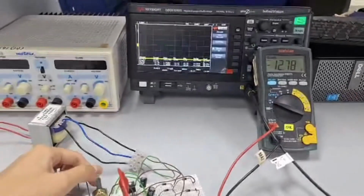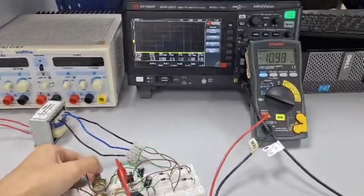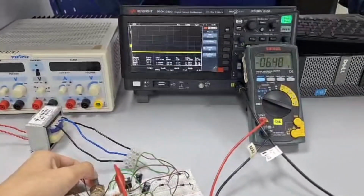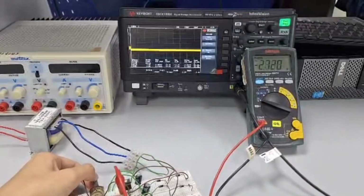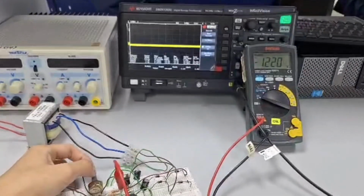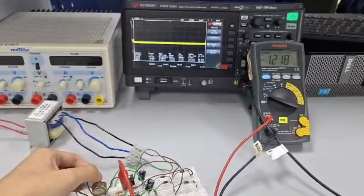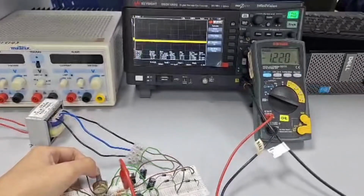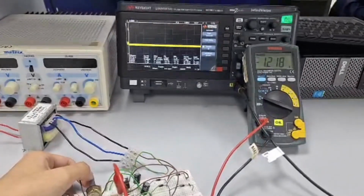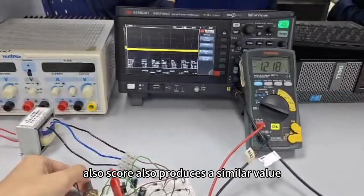So as you can see, as we lower the resistance of the potentiometer, the voltage decreases. We can keep decreasing the voltage until the potentiometer is at 0 ohms, which is when it will display negative 1.220 volts, and you can see the oscilloscope also produces a similar value.